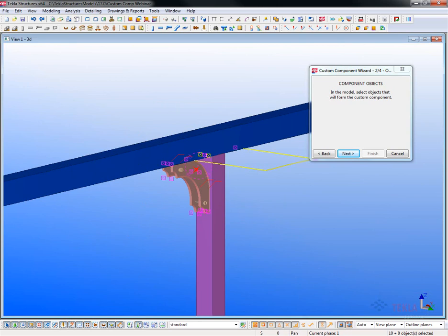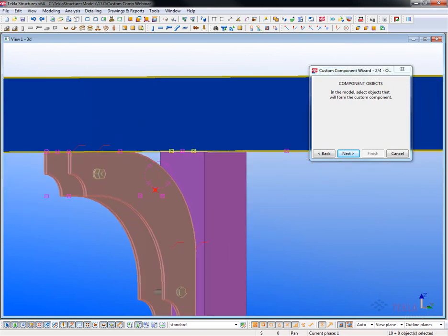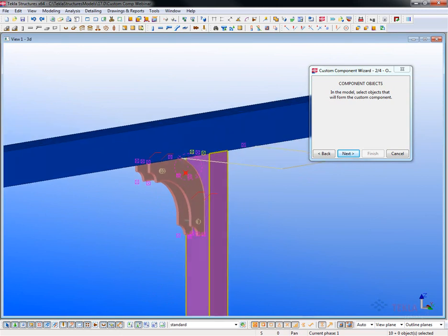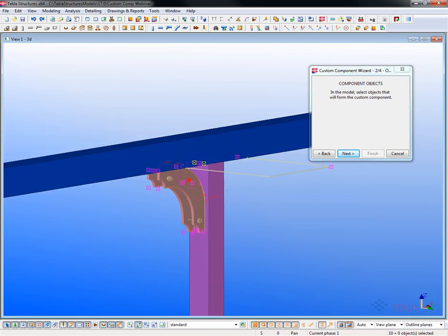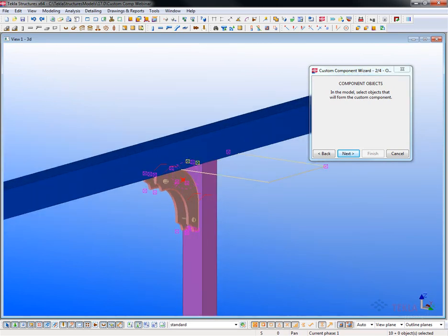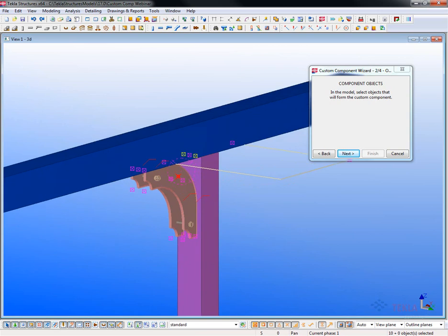I have this fitting that I've selected that's cutting the column down to the underside of the beam. I have the two plates, 4 welds, and these erection bolts that will make up this component. One of these plates I have shop welded to the column, and then it will be field welded to the beam. And then the opposite plate I have shop welded to the beam, and then that will be field welded to the column, and these bolts are used as erection aids.